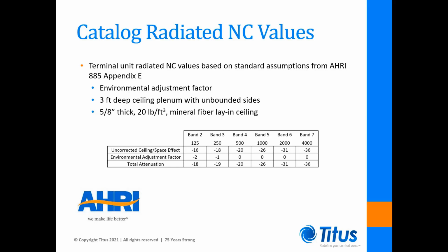This ceiling space effect was developed by a research project called AHRI RP755. It assumes that the ceiling plenum is at least 3 foot deep and unobstructed for a width of 30 feet and has no significant penetrations immediately below the unit. Now let's look at discharge sound.